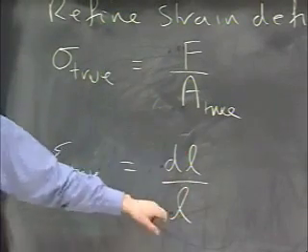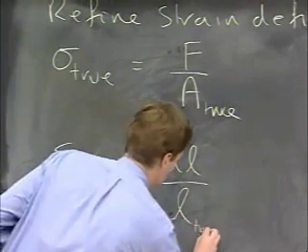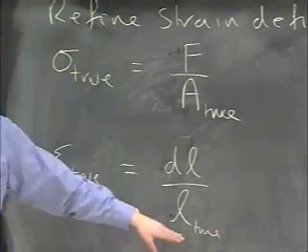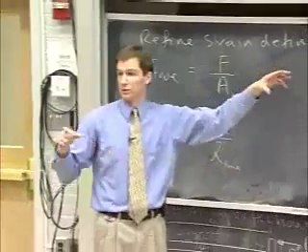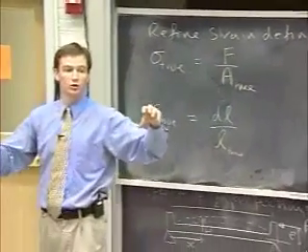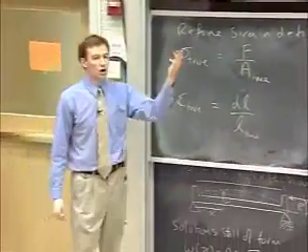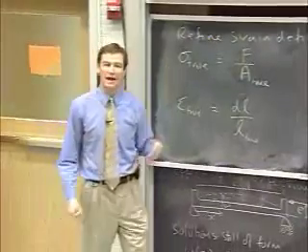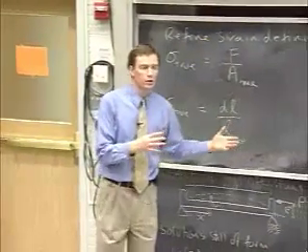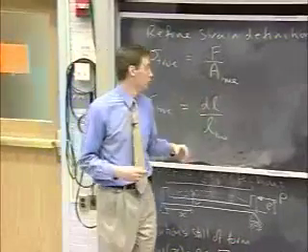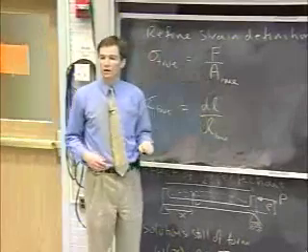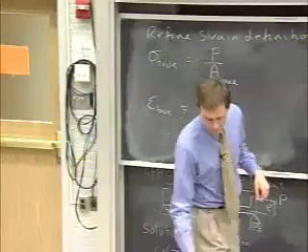It's just that the cross-sectional area and the length are continually changing, or potentially continually changing, as we do these large deformation operations on our material. Elastically, most of the materials we're going to be looking at don't go through large deformations, but in plastic deformation they do, and this allows us to account for that.